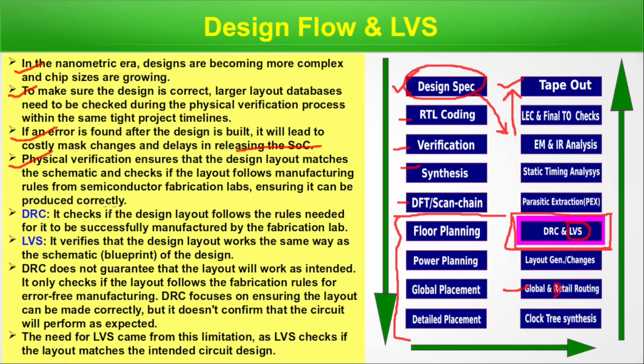DRC checks if the design layout follows the rules needed for it to be successfully manufactured by the fabrication lab. We have to follow it. Although it doesn't mean that the layout is doing exactly what we intended in the design specification. We do that in LVS.